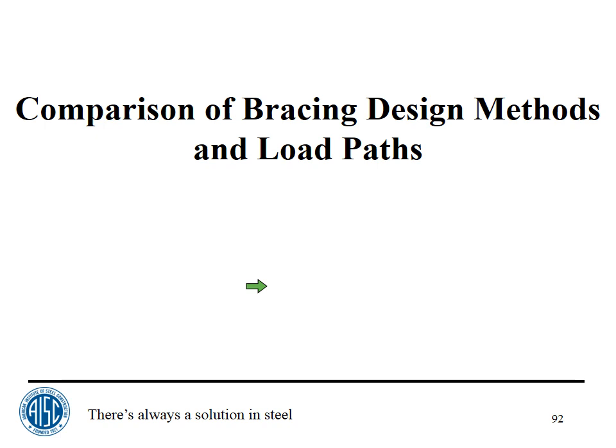But all I had on this building was the footing loads, the column loads at the base of the building. And the loads that these programs gave me agreed with each other, but they did not agree with what was actually used in the design. In some cases, we had like 400 kips in a column in the original design, and we now had 50 or 60. And likewise, we had some columns that had maybe 100 kips in them and now had 300 kips. Yet there was no distress in this structure, and I think the reason is because of redistribution of load.